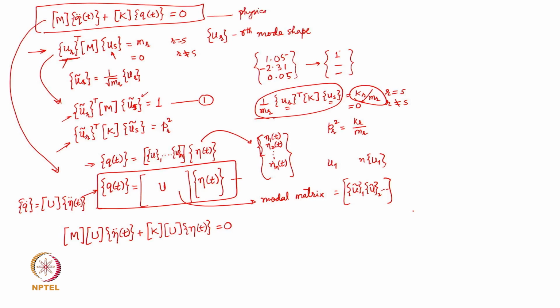So, I am basically going to use this expression and its derivative to transform this equation. These are given in the physical coordinates, the degrees of freedom x1, y1, theta 1, all of these being represented by the vector q. Okay, this is the actual physical response of the system. Now we go to the principal coordinates. They are not the physical coordinates, they are principal coordinates, and the equation of motion is now transformed into this equation of motion.